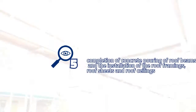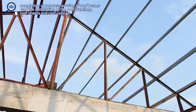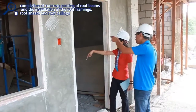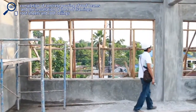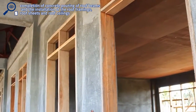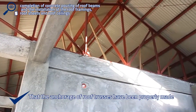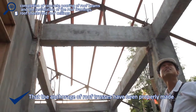Key inspection point 5. Once the contractor has completed the concrete pouring of roof beams and the installation of roof framings, roof sheets, and roof ceilings, the engineer should carry out key inspection point 5. The engineers must check that the materials used on roof trusses, roof sheets, and ceiling conform with the plans and specifications. That the anchorage of roof trusses have been properly made in accordance with the approved plans. Checking that anchorages have been properly made is a very critical point in the process.